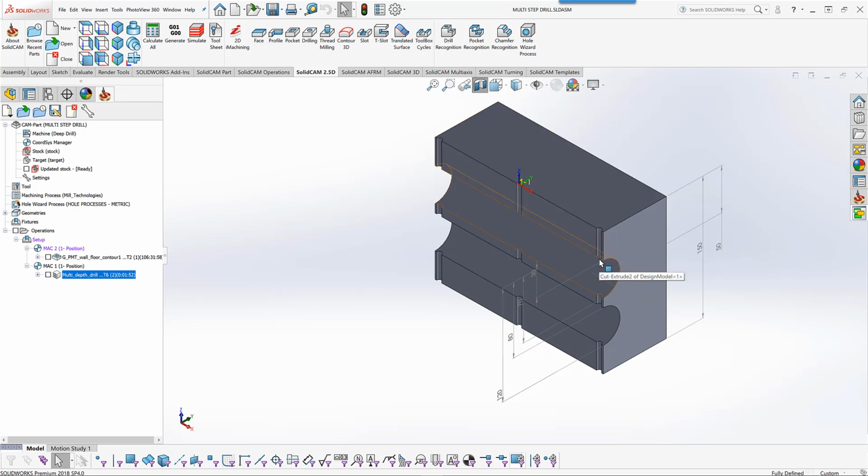over here, then go directly down, continue on down to drill this area, and then continue on down to drill this area without having to peck all the way down as we have done before. So what we've done in this new operation is as follows.